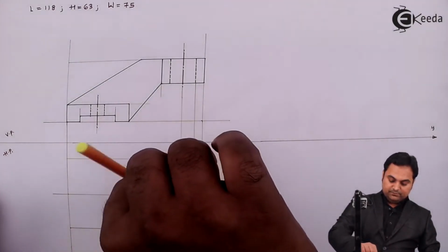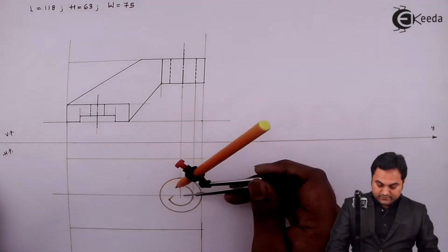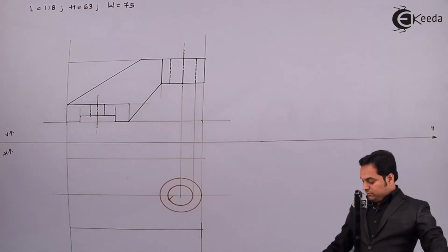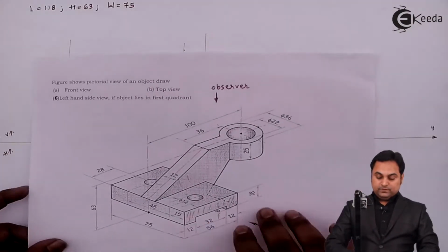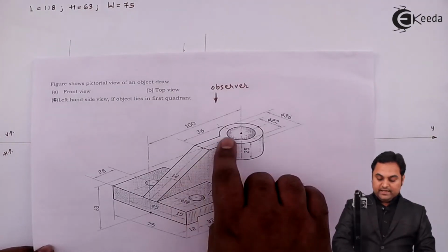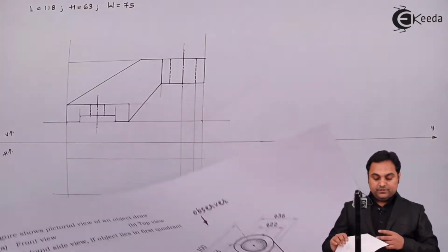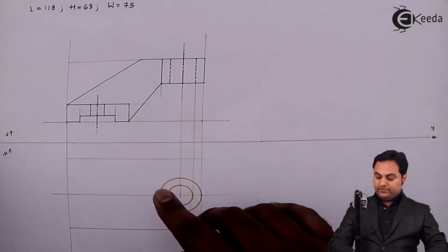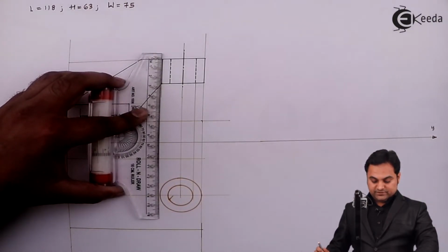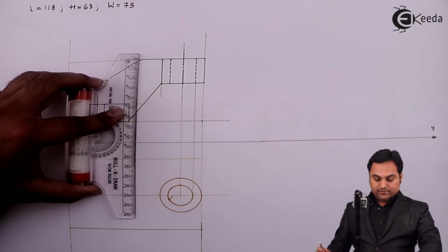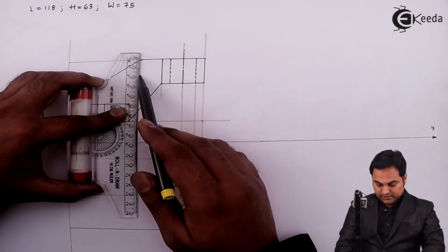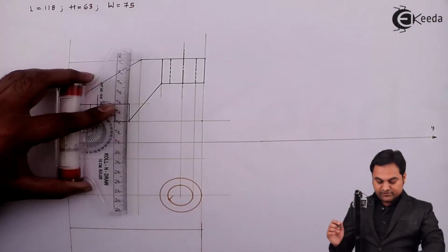Now after I have completed drawing this circle, now looking at the top, this surface is a straight surface having width 12, and it is extended 36 from the center. So that distance from the center is already there in the front view, that I am projecting the distance of the straight surface in the front view, that will be projected down. So this distance is where we are having that straight rib.